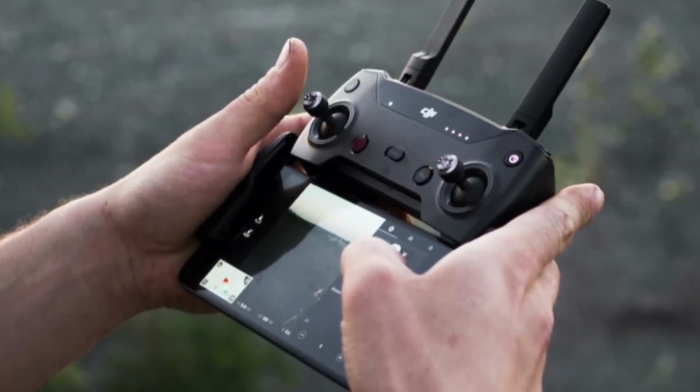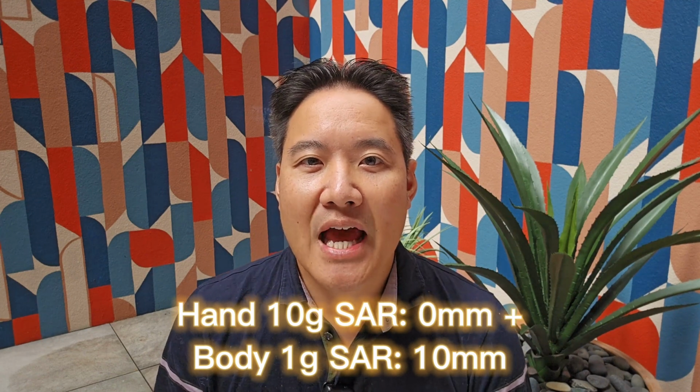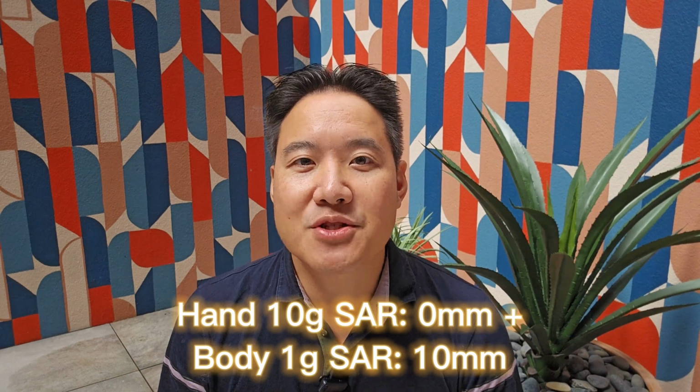And I remember meeting with FCC in person where they developed this a long time ago for small handheld devices. I remember we brought a product that was a little smaller than a little Nintendo Switch. And they basically allowed a touching hand SAR test and additionally required a 1 centimeter air gap test in case a person might be putting it near their body or something like that. But it was a huge gain for manufacturers because the hand SAR is a lot easier to comply at 0 millimeter. And having a 10 millimeter gap for the 10 gram SAR helped a lot since SAR levels exponentially decrease with distance.